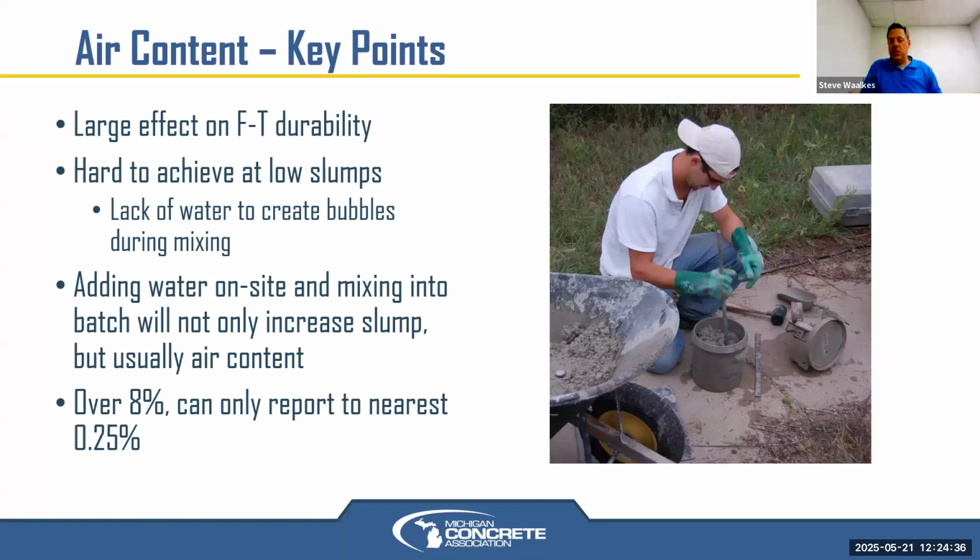When you put some soap on your hands and rub them together and your hands are dry, they're just slimy. But as soon as you put some water on your hands with that surfactant, which is what dish soap is, which is what air entrainment admixture is, now you get bubbles. Now you get foam. So you need the air entrainment admixture, you need water, and you need mixing. Those 3 things are what create the microscopic air bubbles.